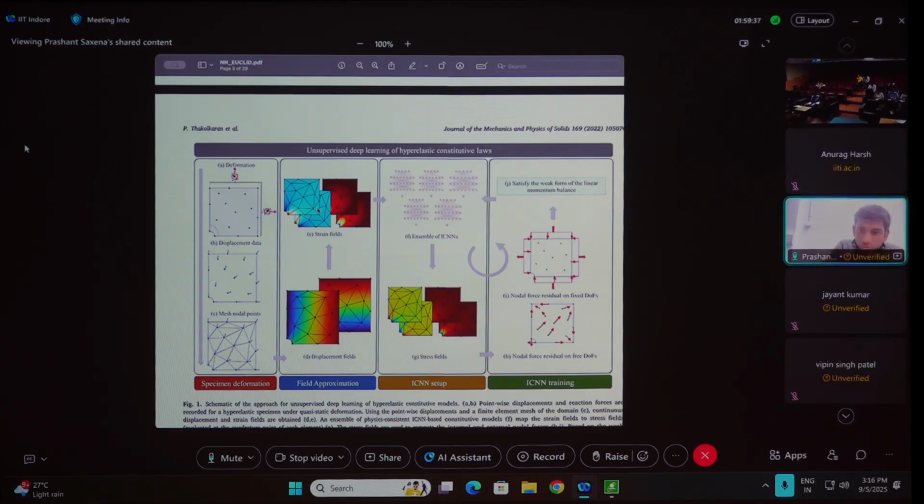and then on that strain field you choose one of the neural networks, which is basically an energy density function. So a neural network now has the role of energy density function, right? So you take the strain, take the energy density function, which is a neural network, and that gives you the stress. And you can do that not with just one energy density function, you can do that with an ensemble.